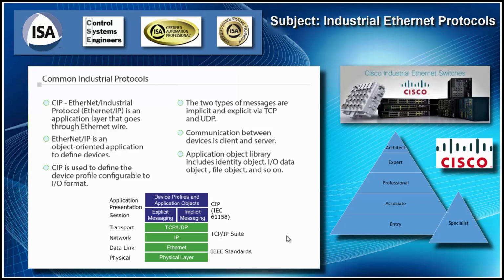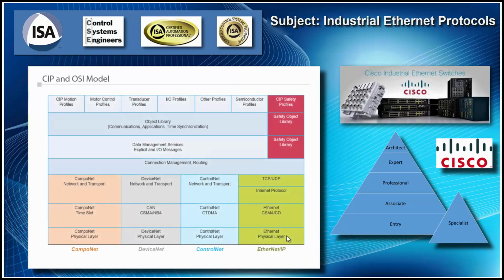Similar to the application protocols in the TCP/IP protocol suite, CIP encompasses a comprehensive suite of messages and services for the collection of manufacturing automation applications. Those applications often include control, safety, synchronization, motion, configuration, and information systems. CIP exists on OSI layers 5 to 7 and is a single media-independent platform that can be used across 4 layers: sensor and actuator layer, device layer, controller layer, and the Internet layer.